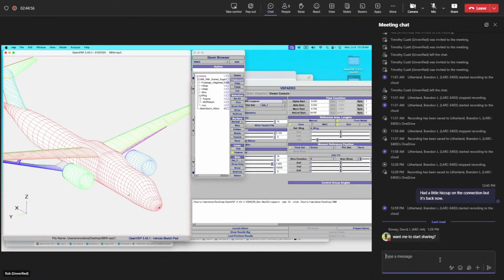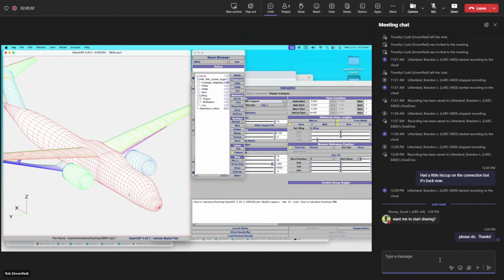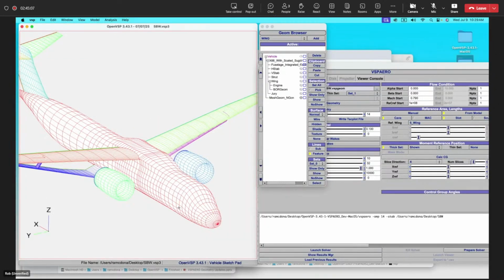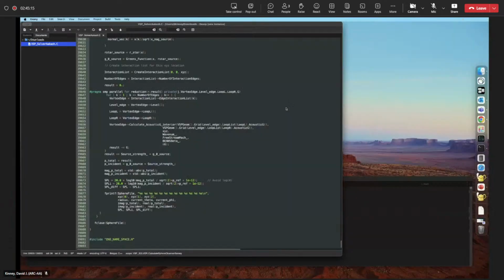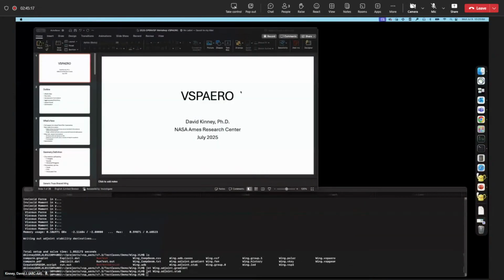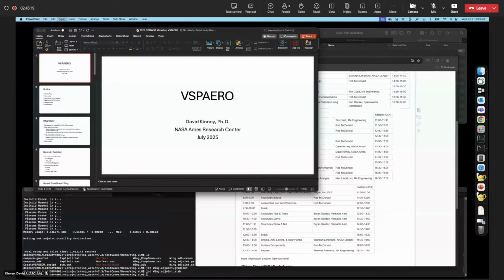But what I find is that it's sometimes unsatisfying when you work with a fuselage. Where that wing body join happens, representing the body as a thin surface isn't necessarily very representative. For example, with a nacelle downstream of a propeller, the main thing that nacelle is doing is acting as a blockage and pushing things away from the slipstream.